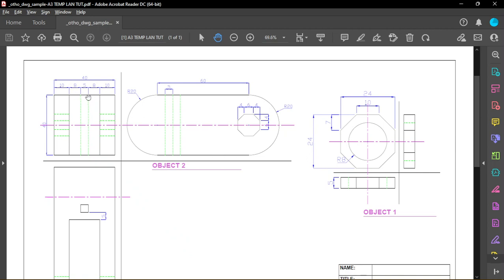But for some reason the precision must have been set to 0 decimal places. That is why it's showing the rounded number, which is 8. Obviously it should have been 7.5. Alright, so we just put 5 in the middle. We could as well measure off 7.5, then draw the 5, and then the balance will be 8.